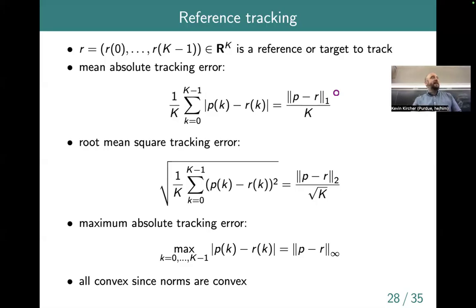I think we talked about this example a little bit last time, but there's a service to the grid called frequency regulation. Basically, the high voltage power grid is an alternating current system. In the US, the current waveform and the voltage waveform fluctuate in a sinusoidal-ish pattern with a dominant frequency of 60 hertz.